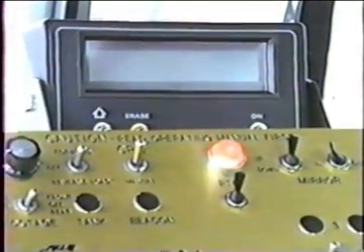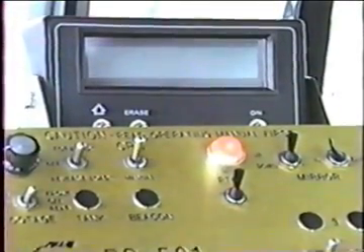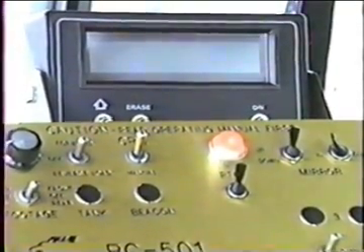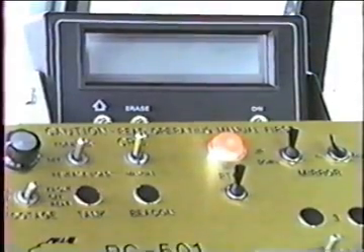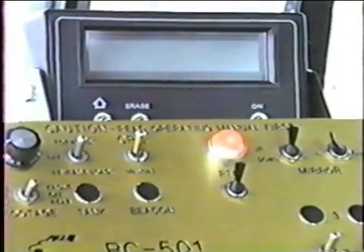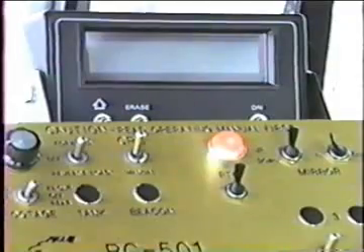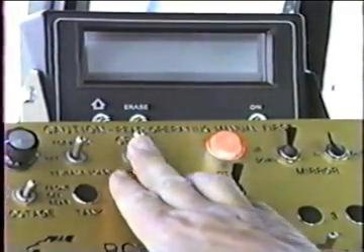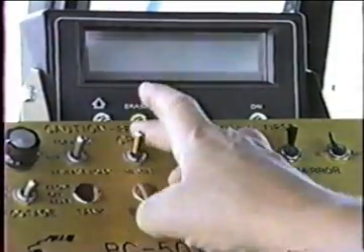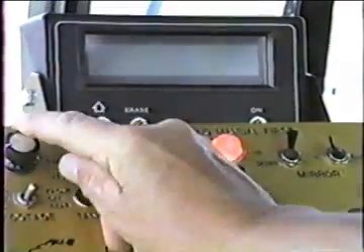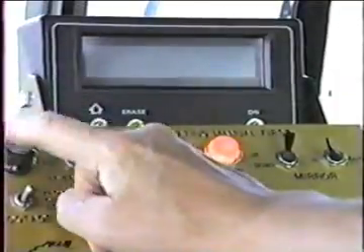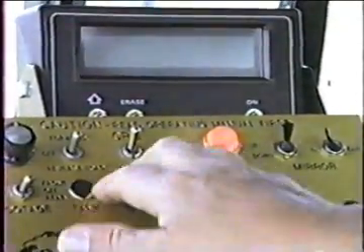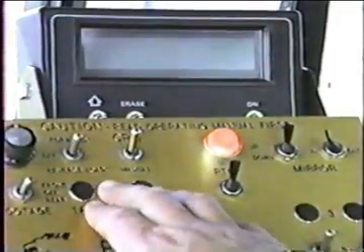This is the Bearcat CRC computerized rate control system. Very simple to operate. When we get to the job, engage the valves at the rear of the tank that are necessary for spray bar circulation. Come back into the cab. A CRC switch on the panel should be in the CRC position. That's up. The manual switches here, always leave them off and the speed turned clear down. They only affect it when we are in the manual position, but that's a better place to leave it.